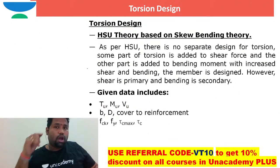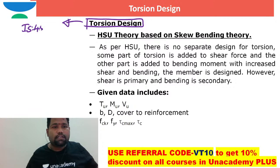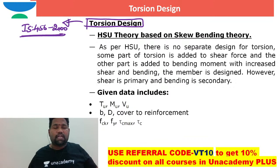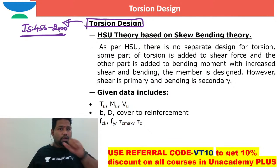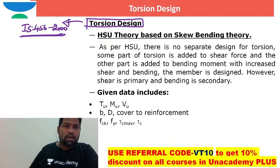That is the big question. So how can you design for torsion? If you see the IS 456 2000 code, it has advocated that there is no separate design for torsion, but when torsion is dominant, then in such case biaxial bending is possible, no?